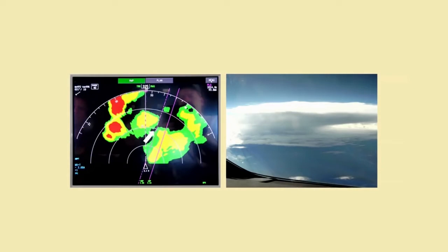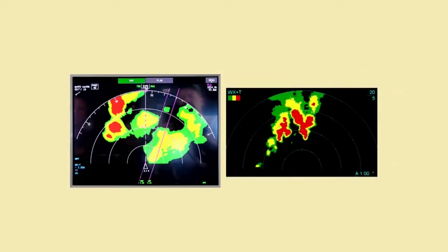This 787 display shows normal thunderstorm activity. The circular shape of the cells and the normal gradient between colors indicates convective activity but no unusual threats. In this case, green represents the outer boundaries of the cells, and the pilot navigated between the two cells containing yellow cores.